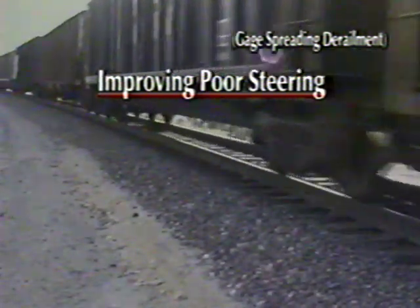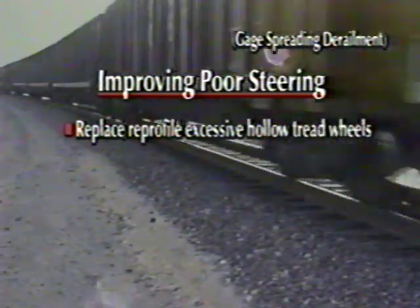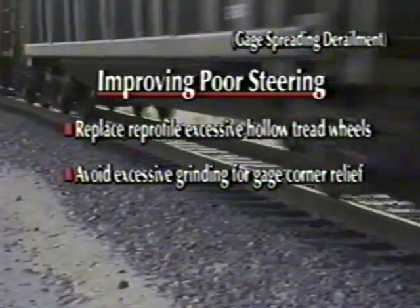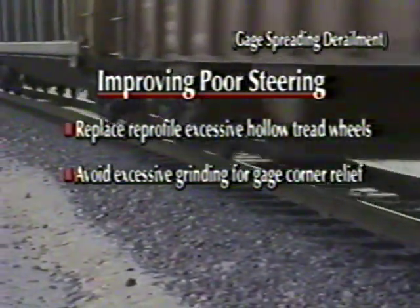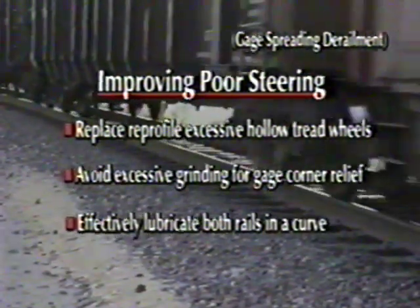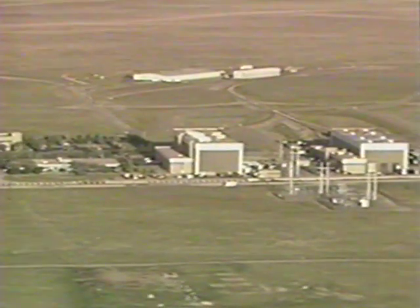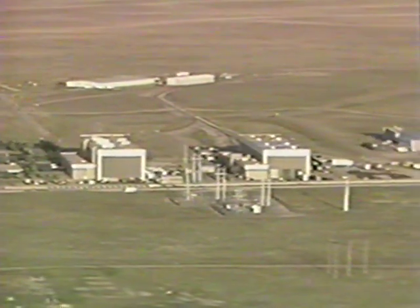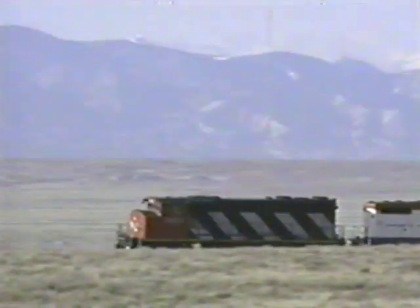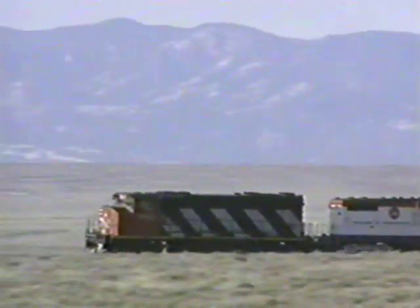Let's review the factors that will reduce poor steering, like avoiding excessive hollow tread wheels through replacement or reprofiling, avoiding rail gauge corner grinding that leaves excessive gauge corner relief, and providing effective lubrication to both rails in a curve. Research efforts by the Transportation Technology Center, the FRA, and the railroads are still investigating appropriate guidelines that would define condemning profile limits and provide the tools to measure profiles.